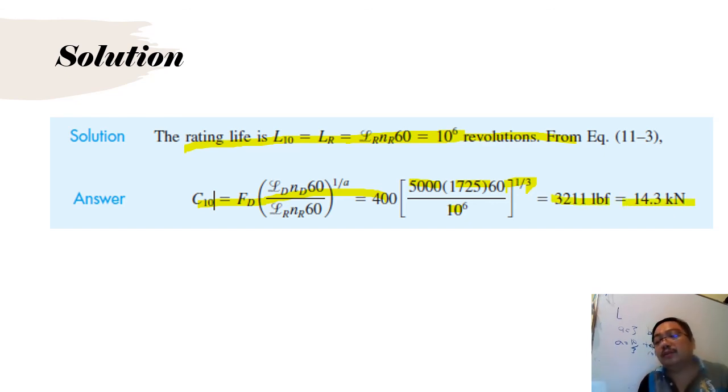So what you want to do with the value 14.3, you go to the catalog for the bearing, like you go to the catalog in the supermarket, Tesco, IKEA and everything. You see what is suitable for 14.3. C10 equivalent to 14.3, and you see all the data and you choose. This is what you choose. C10 is the suitable bearing for your application, 14.3 kilonewton. That is basically how you choose from the catalog.